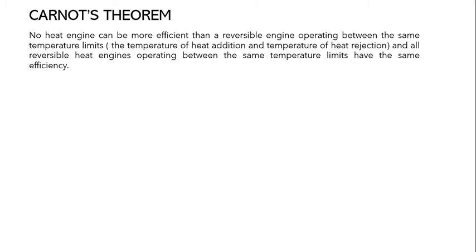So now come to a theorem which is termed as Carnot's theorem. According to this theorem, it has been stated that no heat engine can be more efficient than a reversible heat engine operating between the same temperature limits, which is the temperature of heat addition and the temperature of heat rejection, and all the reversible heat engines operating between the same temperature limits have the same efficiency.